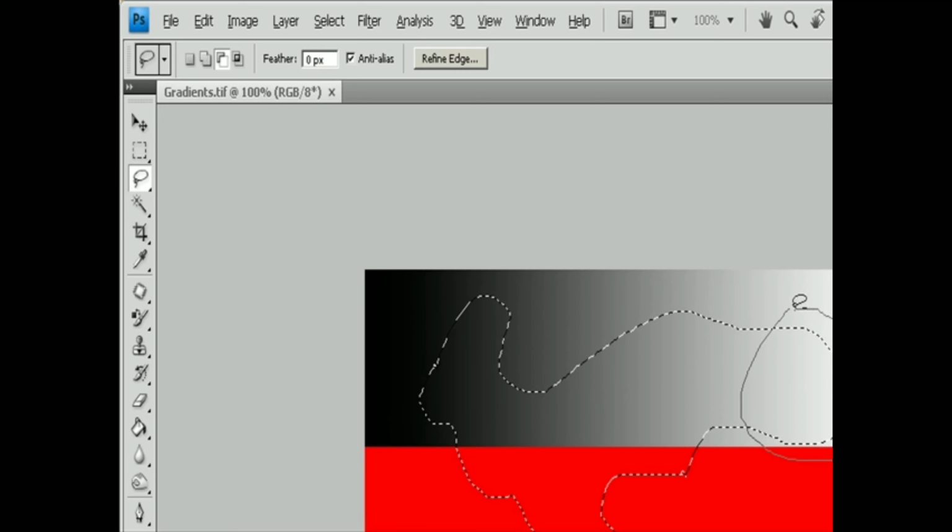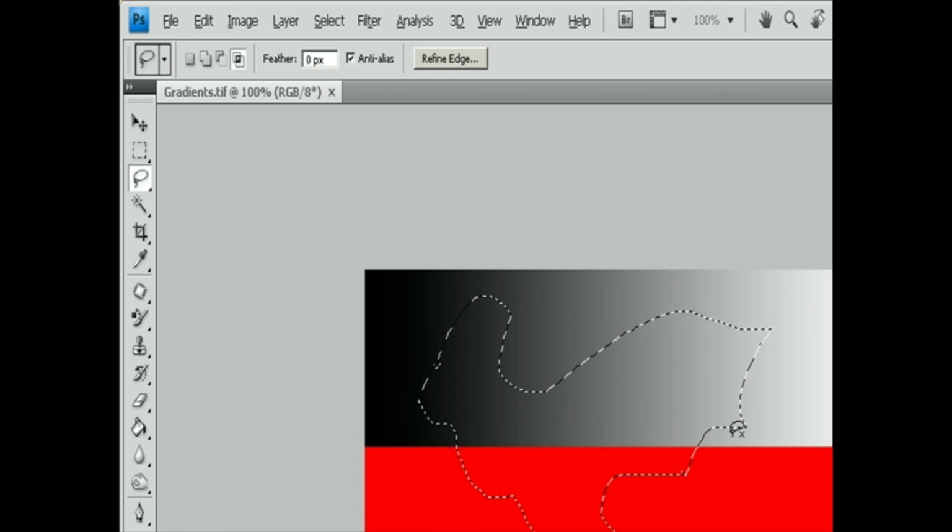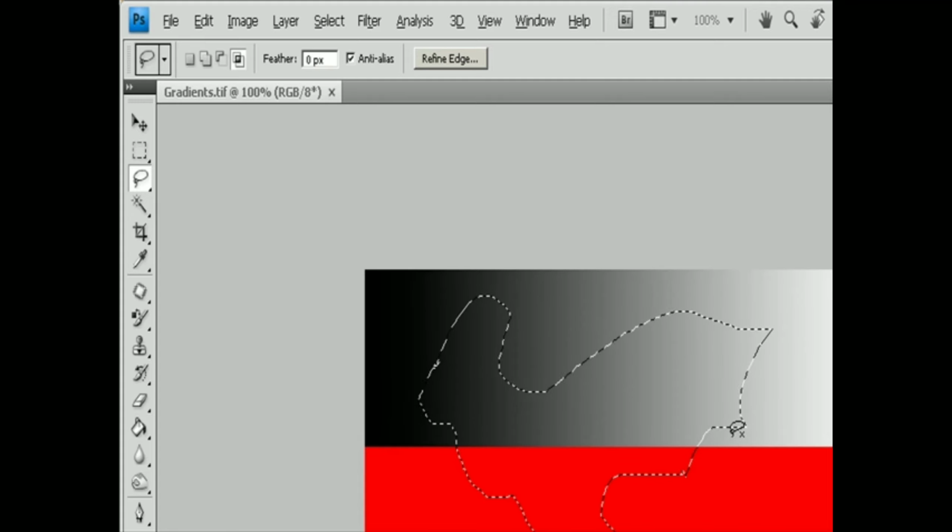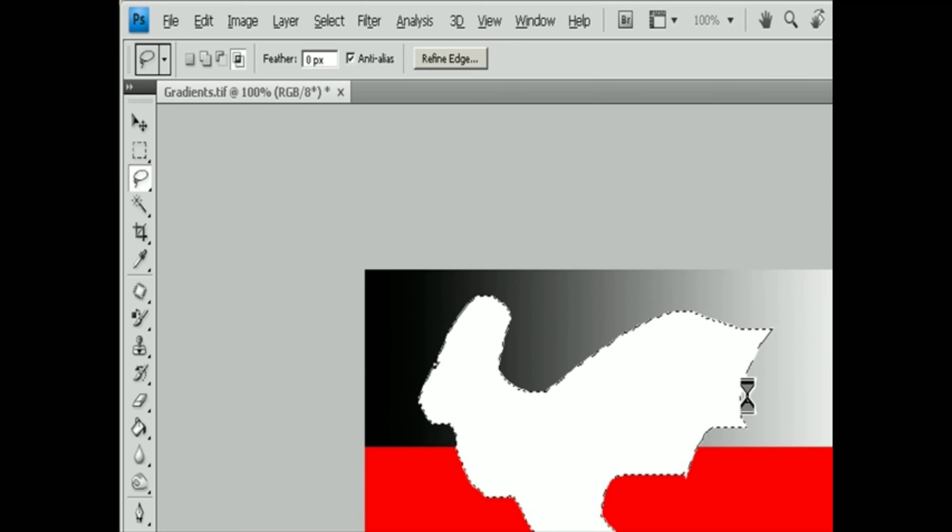5. To draw a straight edge selection border when no other pixels are present, press Alt in Windows or Option in macOS and click where segments should begin and end. You can switch between drawing freehand and straight edge segments. 6. To erase recently drawn segments, hold down the Delete key until you've erased the fastening points for the desired segment. 7.